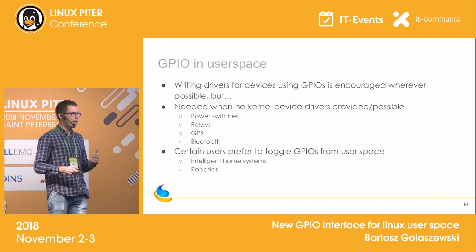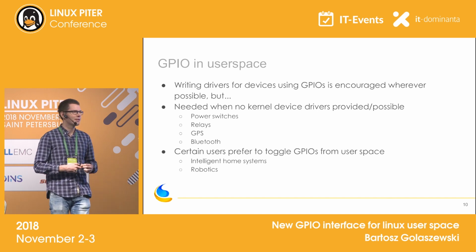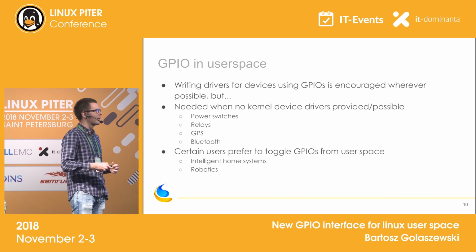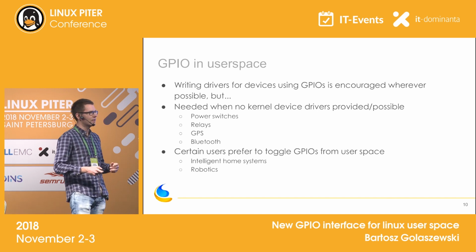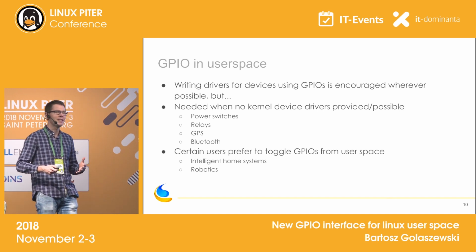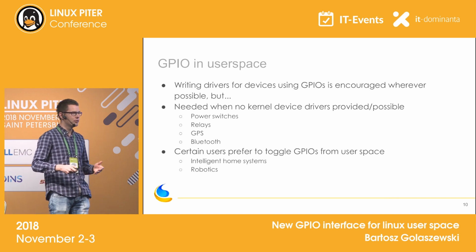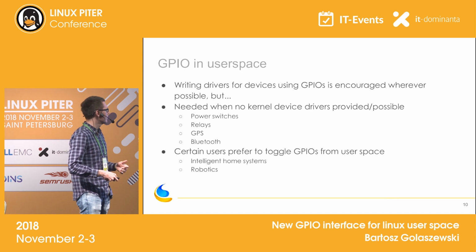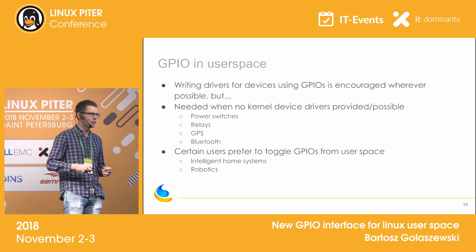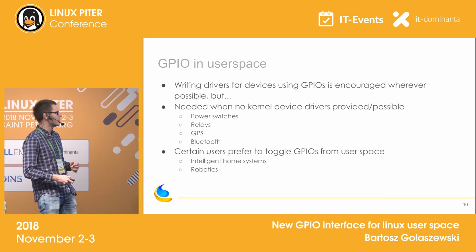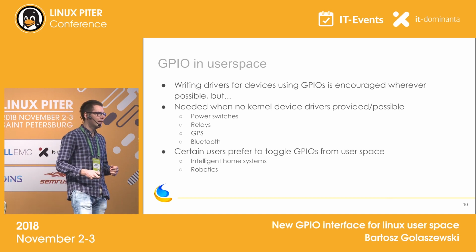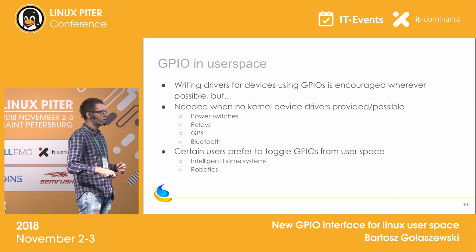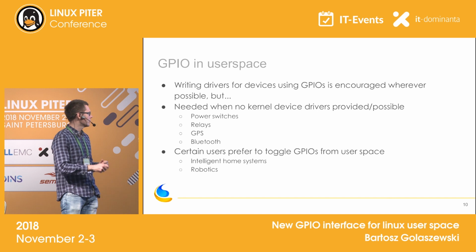Sometimes, and I see Johan in the room, so he's taking care of that, but up until recently, GPS devices existed solely in Userspace. You would talk to a GPS over a serial port, virtually a serial console, and if you wanted to disable the device, you could wire the regulator to a GPIO and simply toggle it from Userspace.